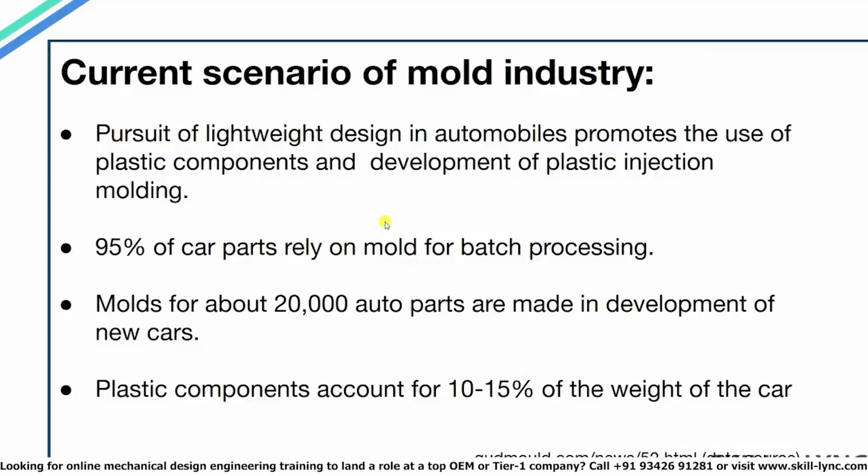Plastics are used for interior, exterior, and even structural parts in the manufacturing of cars. If we look at high-end luxury cars, their main focus is on the interior of the car. They usually require plastic with a mirror finish for the car interiors. So these plastics are manufactured using injection molding, and the mold tools used for the manufacturing are highly polished.